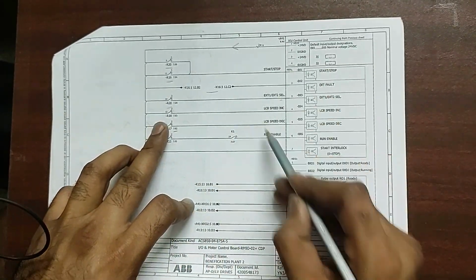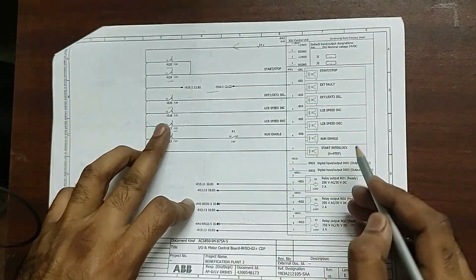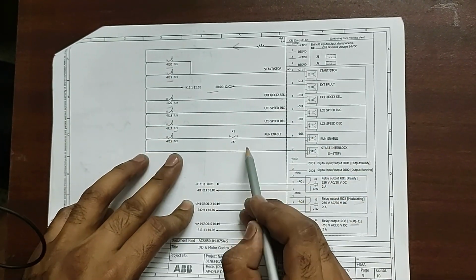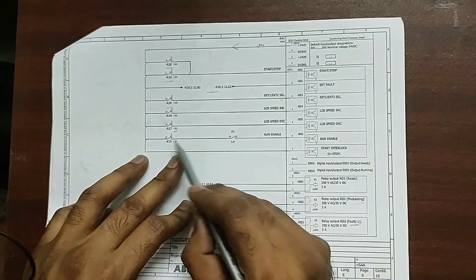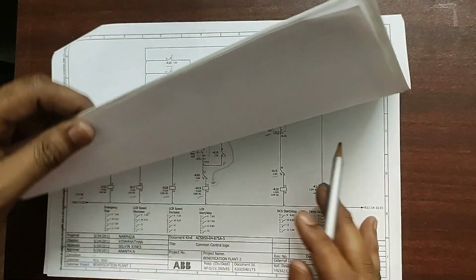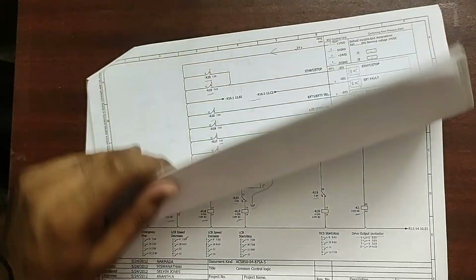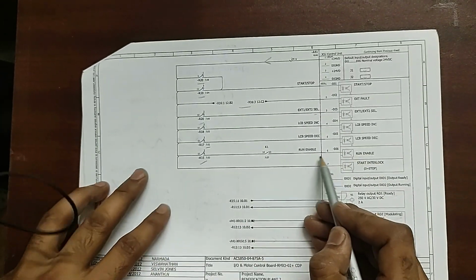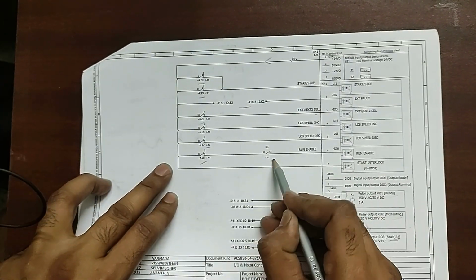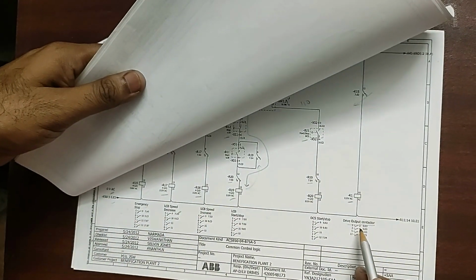24 volt, 24 volt is important. See, drive is a very complex, very delicate part, so it works on 24 volt. Similarly, for speed increase and decrease, you have 24 volt coming here and here. Key 15 is high. Key 15 means everything is in condition. Everything is okay, it will give the high command to K1. So both have to be high. K1 is the output contactor.